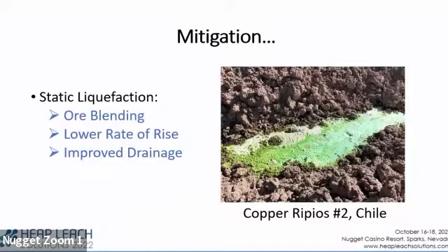That's pretty unusual material. So typically you can manage it with a rate of rise of your dump of 5, 10, 15 meters, something you can live with. Your footprint gets bigger because you can't go up to that 100 meters high as fast as you thought. You might not be able to go up to 100 meters.